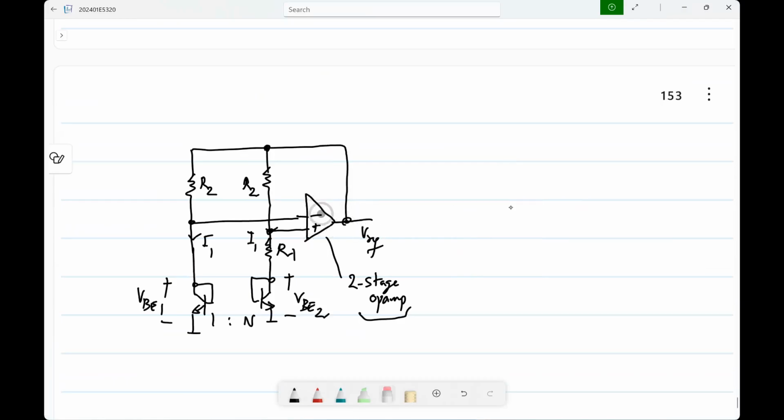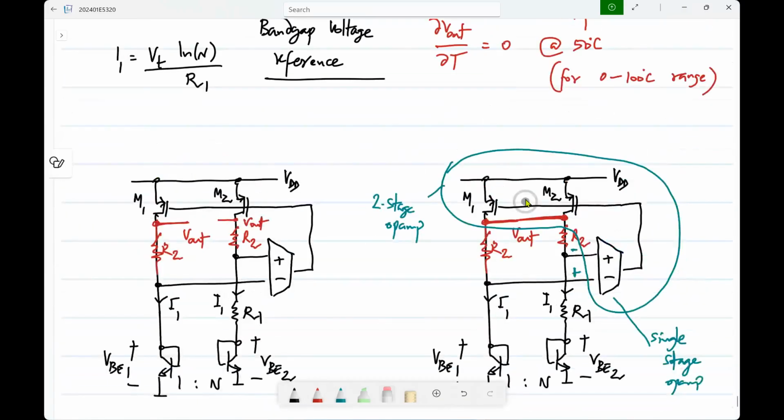Okay, so that entirely depends on the output stage design. That is also the reason to tie these two together. Let's say you are taking the output only from one side and you draw current. What happens then is M1 and M2 will be operating with different conditions. So that will also affect the matching.